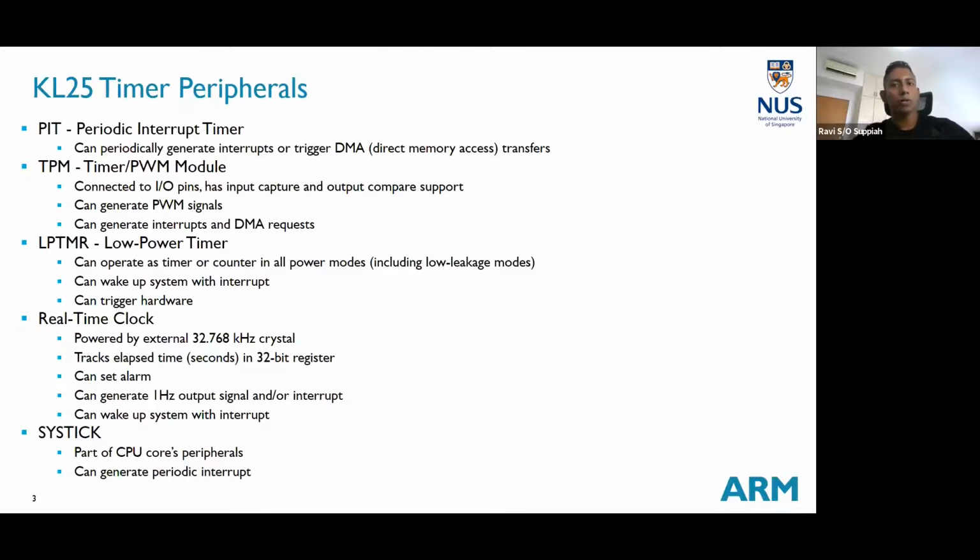In terms of the timer peripherals that we have in the KL25Z, there are quite a lot of timing subsystems. The periodic interrupt timer, we will briefly look at. The TPM, which is the timer and PWM module, is the focus of today's lecture. At the same time, we also have the low power timer configuration, and the real-time clock. And there's an internal SysTick that is used by the core peripherals.